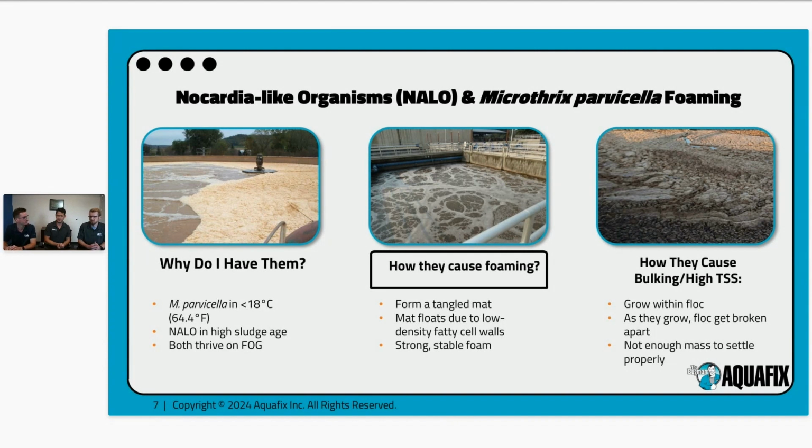Yeah, and a lot of times the foaming is kind of the visual indicator that something's going wrong in the aeration basin. So it's kind of like the last thing, like there are so many filaments, they're coming up into suspension. Aesthetics could be a thing too. A lot of operators obviously take pride in their plants, wanting them to look good, take tours, that kind of stuff. Having the foam is just unsightly. Also, if you look to the right, it can get really bad to the point where, like Tyler brought up, it can start having mechanical issues and creating oxygen diffusion issues, DO issues. And as these guys said, it just points to an underlying issue.